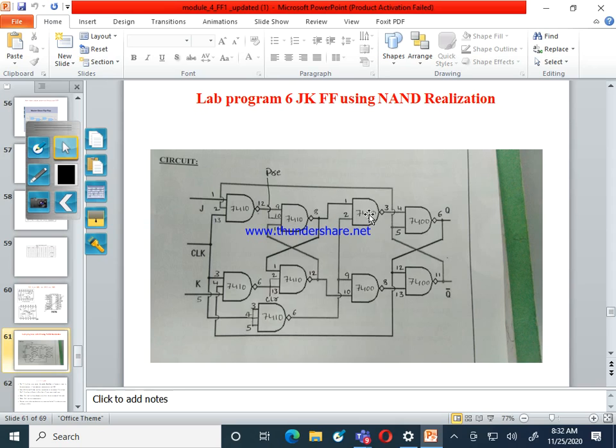Okay, that is your choice. You can take this NOT gate as 7400 or 7410. There is no restriction on what type of NAND gate to take, because actually there is only one input for the NOT gate. Because of one input, you can take 7400 or 7410. In both cases, the unconnected pins will be connected as a short, and the output taken to the slave.